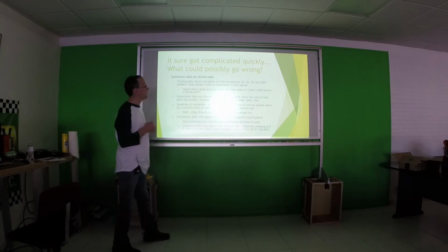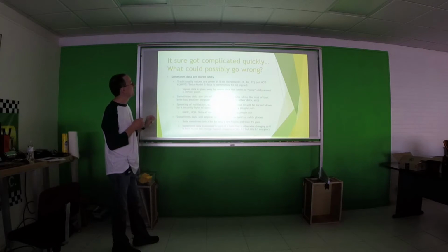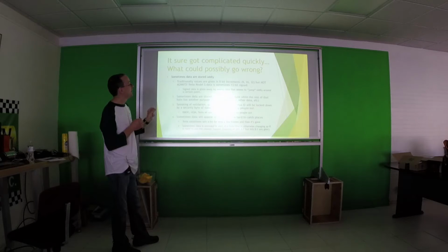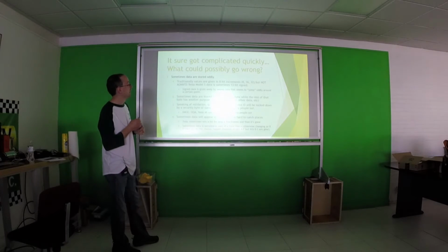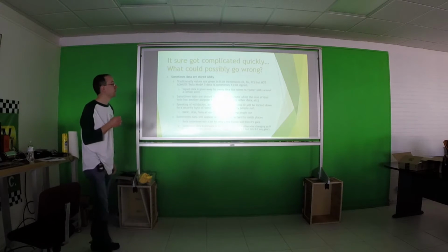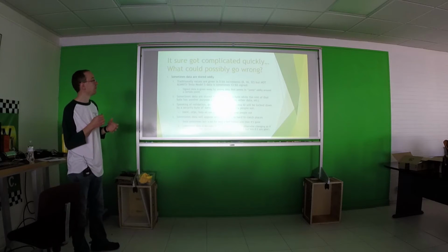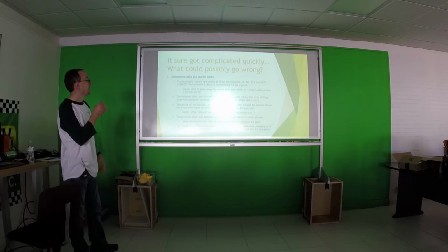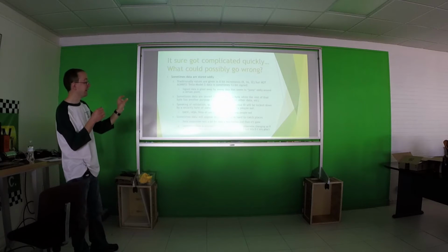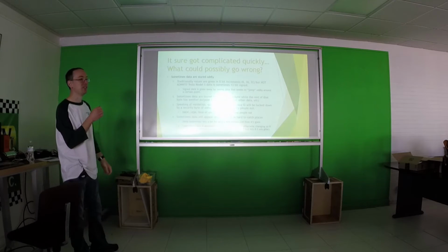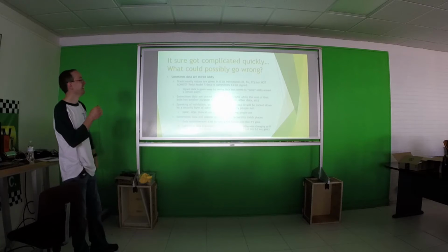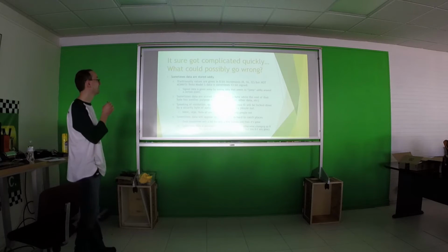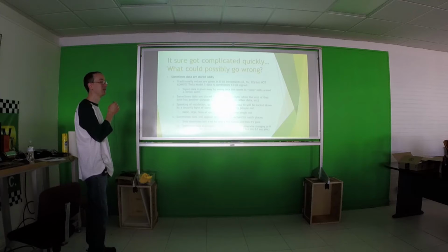Sometimes on the Model S data, a 16-bit signed integer would have been normal. What they did is take the top 3 bits in a 16-bit integer and put a counter in there. So the top 3 bits go 1, 2, 3, 4, 5, 6, 7, 1, 2, 3, 4, 5, 6, 7. When you look at that data, you see huge jumps as the counter counts in the highest position, so the data looks terrible. You have to try to get rid of that. That sometimes throws you off.